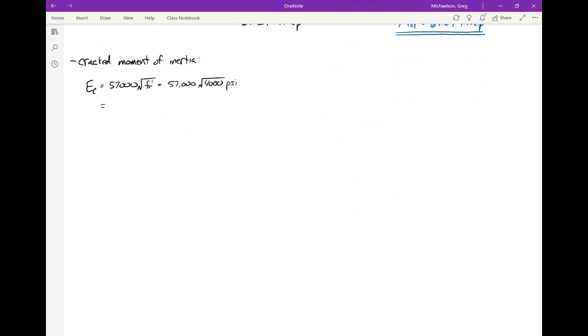And when you plug and chug that out, it's a big number. It's 3,604,996.53 psi. Or if I'm turning that into ksi, I just divide by 1,000. And so dividing this by 1,000 comes out to be, we'll just say it's 3605 ksi. And remember, that was actually one of the things that we had to compute in this problem. The problem asked for Ec and Ie. So I'm going to report that in the end as our final answer, but I'll wait and do that later.